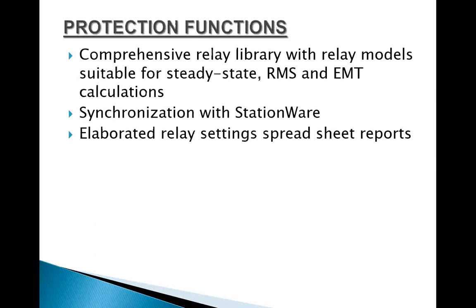Protection functions include a relay library, different relay frames, and relay models with company standards and specifications. We just have to click and select our desired relays. Suitable for both steady state, RMS, and EMT calculations. Synchronization with StationWare is possible with the software. Elaborate relay setting and spreadsheet reporting can be done through the extended protection functions which the software provides.